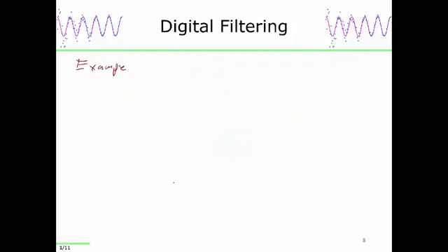I'm going to give you one that's a little clearer. We're going to think about this same process. We're going to build a bandpass filter. And we're going to do it in 2 steps. First step is going to be a low-pass filter, and then the second step, I bet you can guess it, is a high-pass filter to remove the DC. So a low-pass filter, what would that look like in the frequency domain? You'd want to retain all frequencies up to some cutoff.